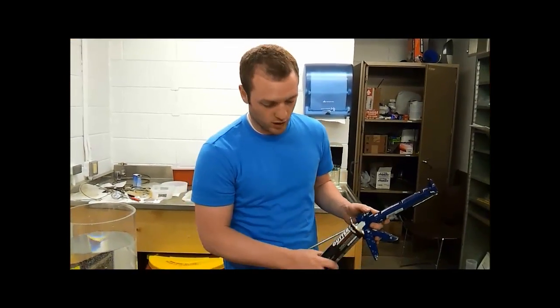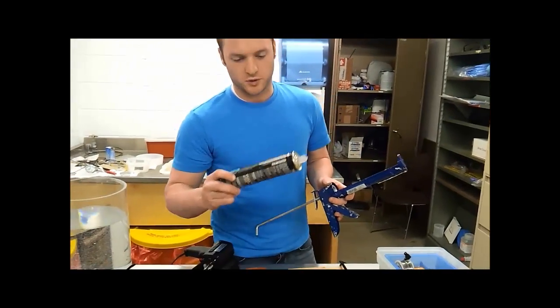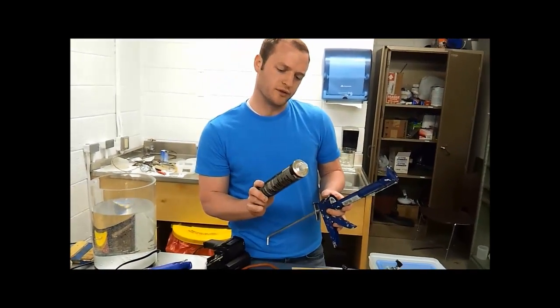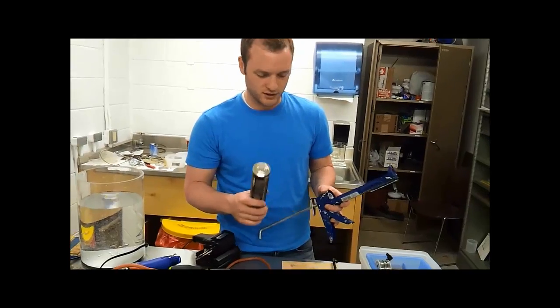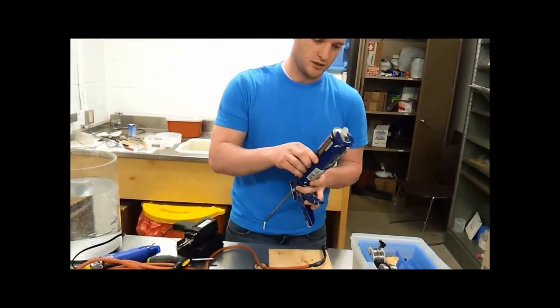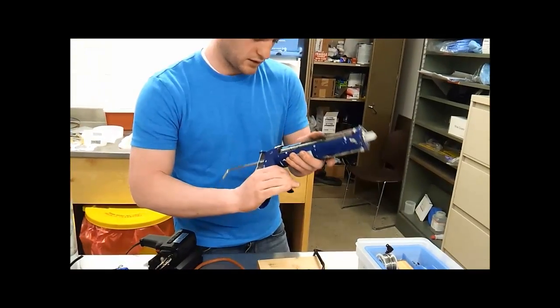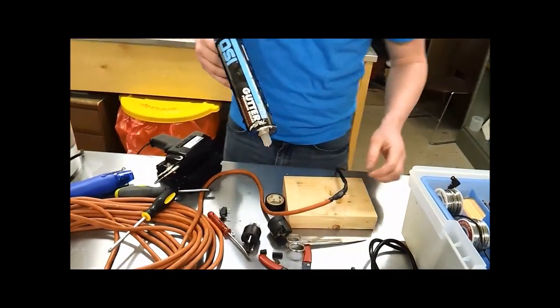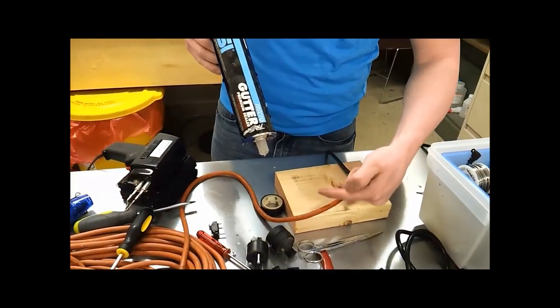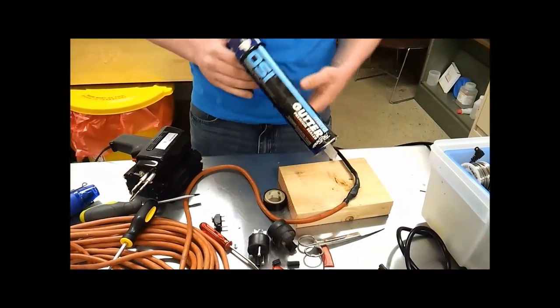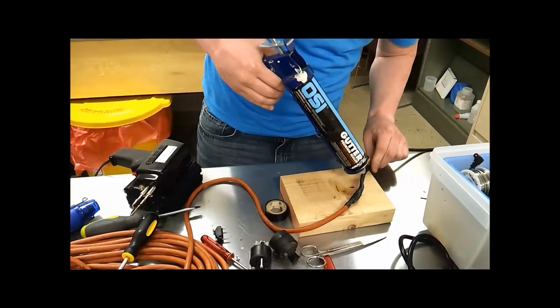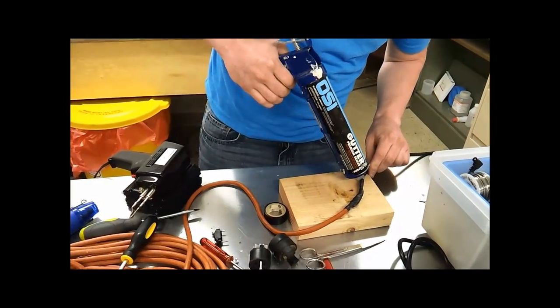So for the next step, we're going to waterproof this. And so we're going to be using, this is actually, I think for gutter, a waterproof sealer. So you're going to need to get that, some caulk and this gun. Okay, here we go. So you're going to want to cover probably up to about here and here completely with this sealer. And don't be afraid, lay it on nice and thick.